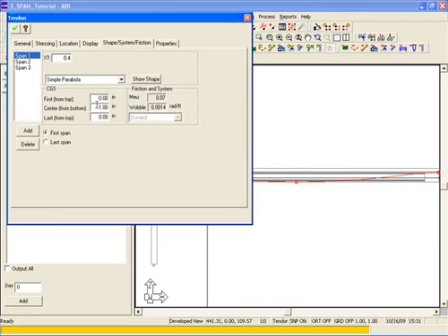The CGS points for this particular bridge will be 31 inches at the end, 27.5 inches at the midpoint, and at the supports we'll use 13.5 inches. Again, we'll use 27.5 at the midpoint and 13.5. And at the end will be 31 inches.